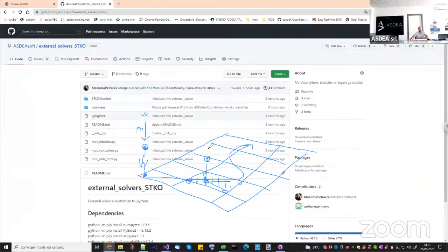Well, this basically translates into transferring this force here, which is W, onto the other nodes. And these projections are proportional to the distances of the projected node from the other nodes. For example, if this node is actually here, the entire load goes here. If it is at the centroid, it will be divided by 4, and so on.